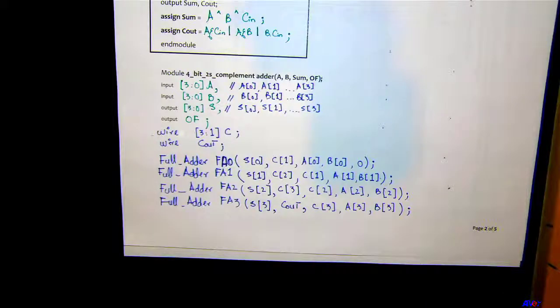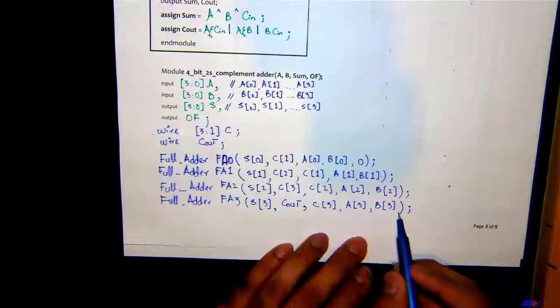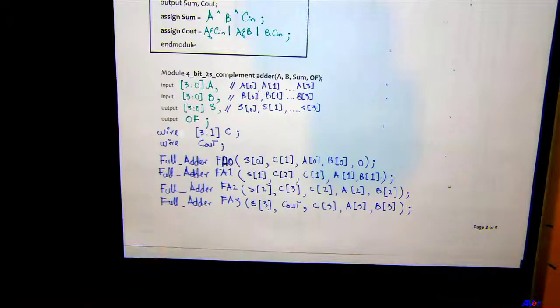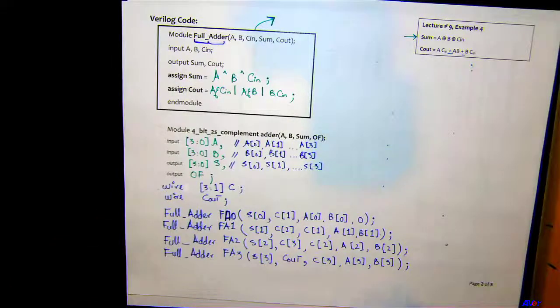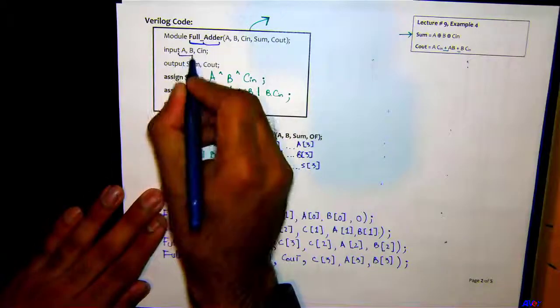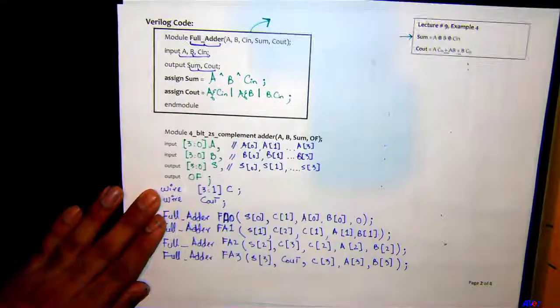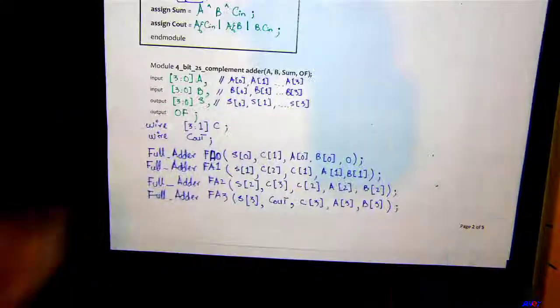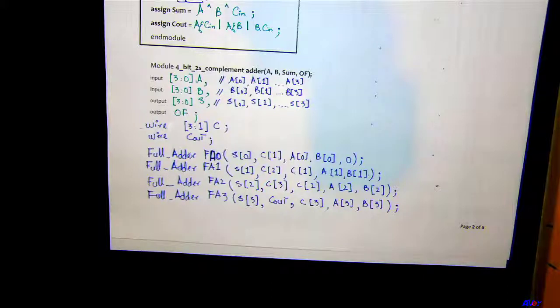If I just add one more variable to it, if I just say comma C2, what would happen? What do you think? Is it going to throw us an error? Yes, it will throw us an error because it can only accept 5 arguments in there. Okay, because that's how your full adder is. Your full adder is only accepting 5 arguments. 3 of those are inputs, 2 of those are outputs right here. Okay, you'll get a better grasp of it when you do the lab.